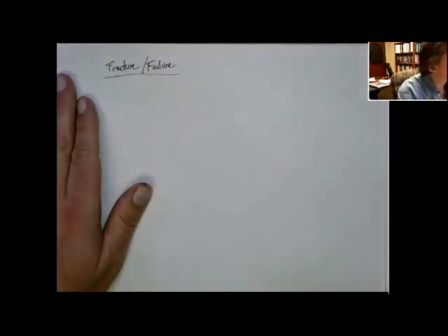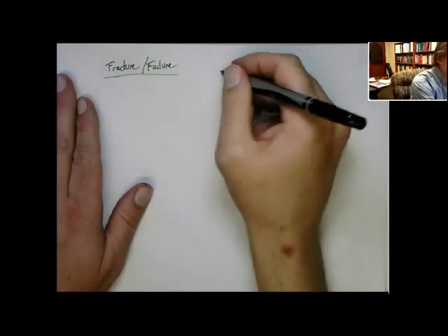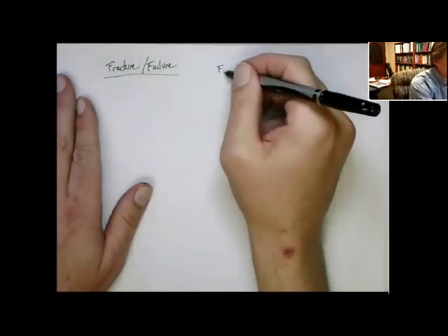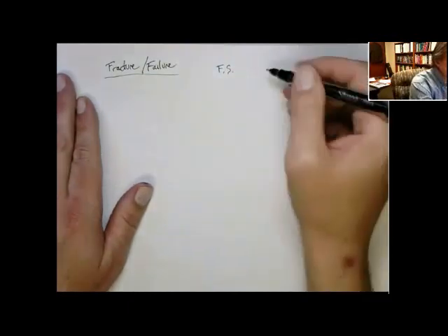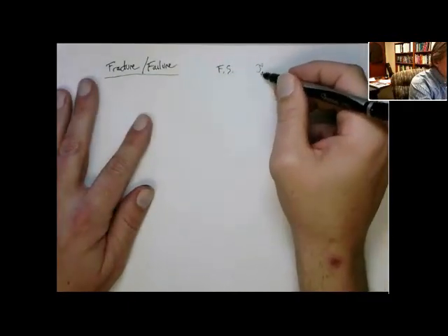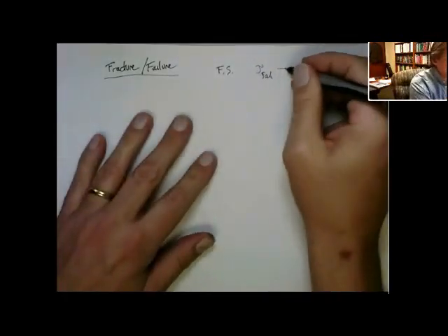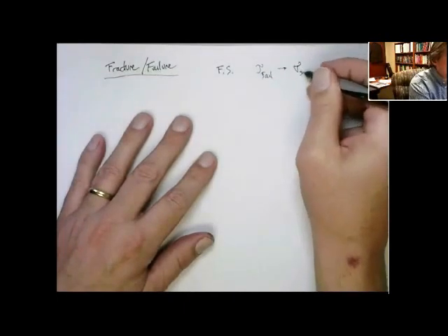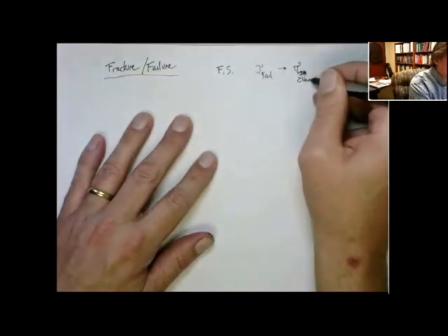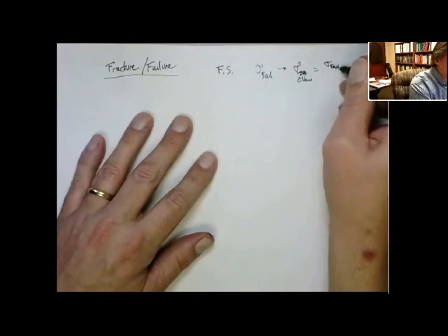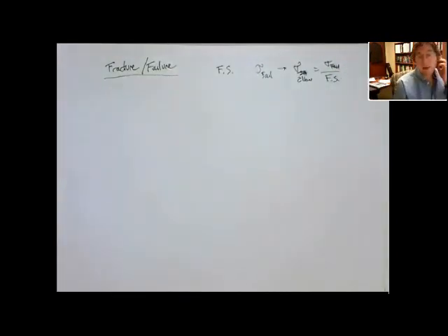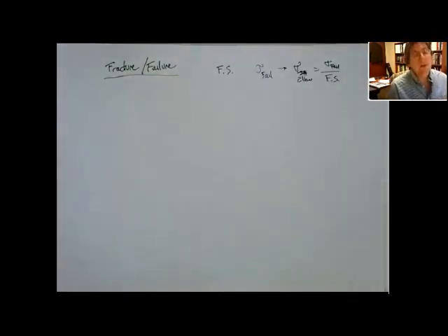No, in the previous chapter, we talked about this notion of designing axial elements and factors of safety and whatnot. In those situations, we had a failure strain for a particular material, and given the failure strain and the factor of safety, we get an allowable stress. Allowable was the failure stress over the factor of safety, right? So the factor of safety basically knocks it down, gives you a margin for uncertainty, errors, overloads, unexpected things. That's where it comes from.